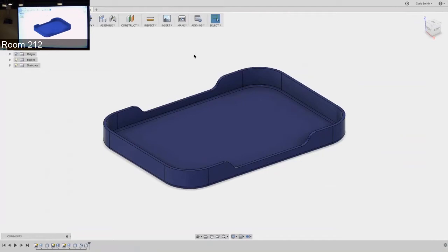But the point is that with 3D printing, and this is on one of my slides, you're going to want to take what you would normally think of and multiply that by some factor to deal with the error. It's going to depend on what printing process you use. Do be aware that this material will rub away. So if you have a metal part that you want to interface, if you can physically get it in there, you can probably round out whatever shaft or hole.